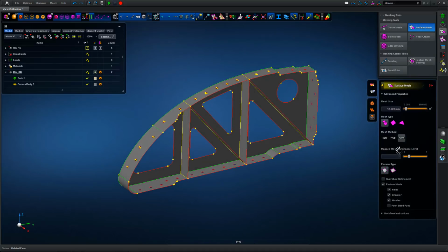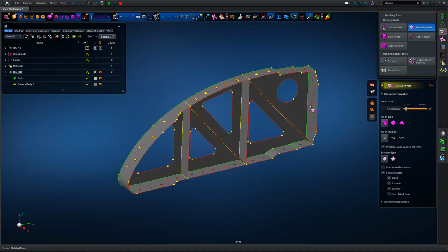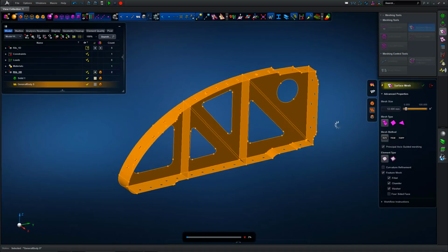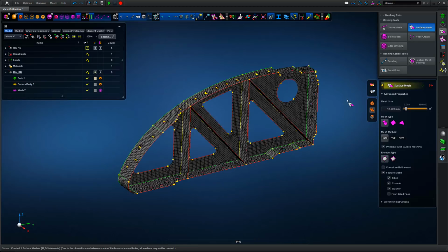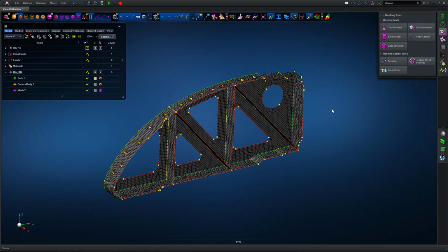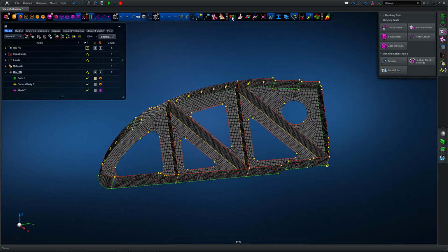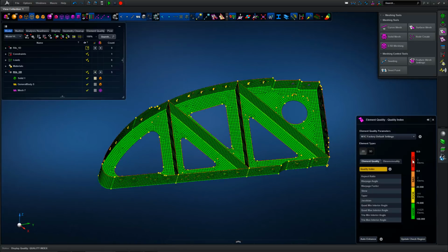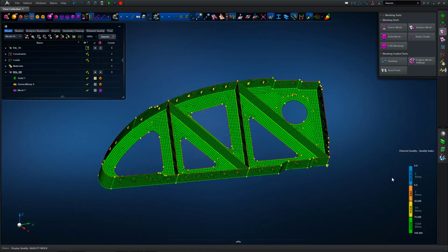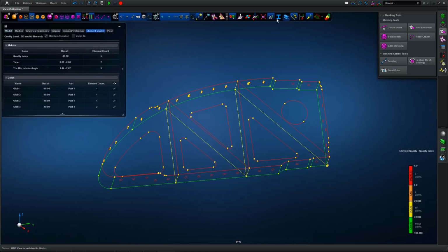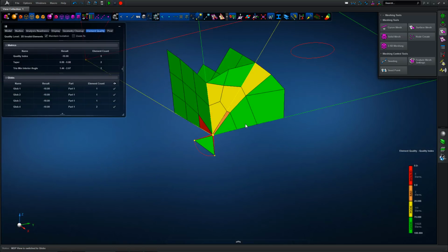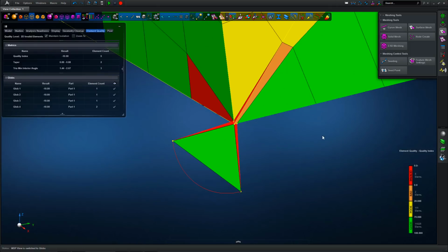So now we'll get into surface meshing, again using the mixed tri and quad with the appropriate element edge length, 12.5mm in this case. Mesh those quickly. We've got the feature mesh settings turned on such that we get good control over say a ring of elements around the hole and that type of thing. So checking the element quality, let's have a look. Yeah, we've got some poor elements, or rather some invalid elements at one particular location.